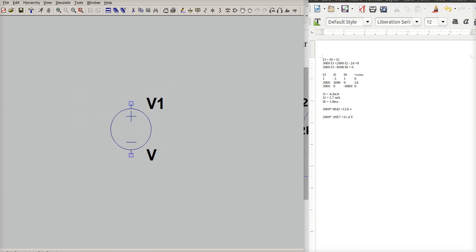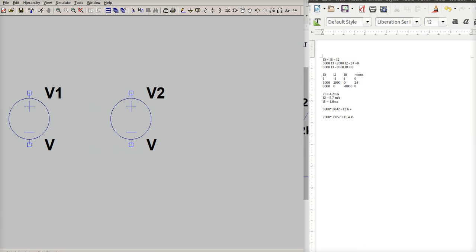And then it's following my mouse around. Now I haven't clicked yet, it's just following my mouse around, but when I click, it plants it in my circuit, and now it's wanting to plant voltage 2. This is where I told you you either have to hit the right mouse button or the escape key to go back to a cursor. So we want one voltage source. We want 3 resistors. And so I clicked on the resistor icon and I dragged it down.